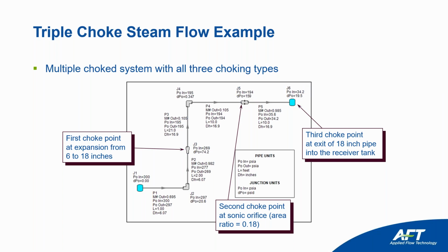Well, wherever the first location of your choke point is, that's what sets your choked mass flow rate, M dot C. Keep in mind that in a flow path, the first geometry that you have sonic choking, that's what sets the flow rate through the rest of the system, because mass cannot be created or destroyed. And so here we know that the flow rate would balance.